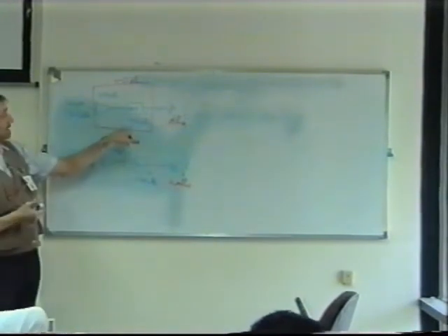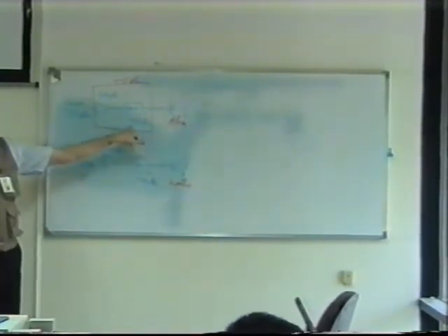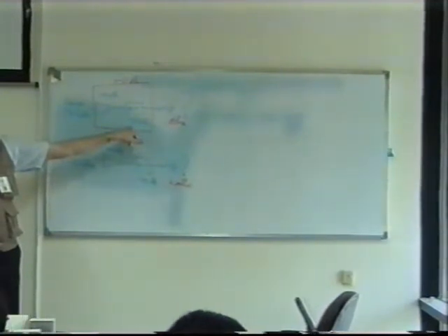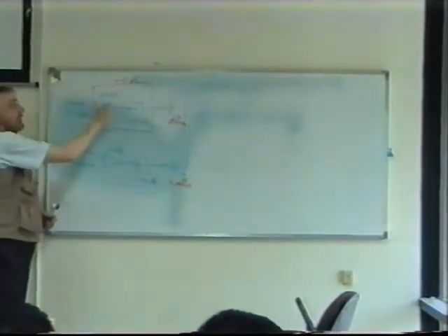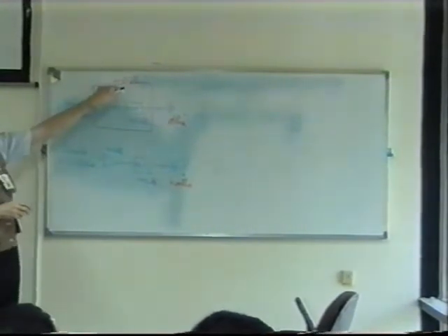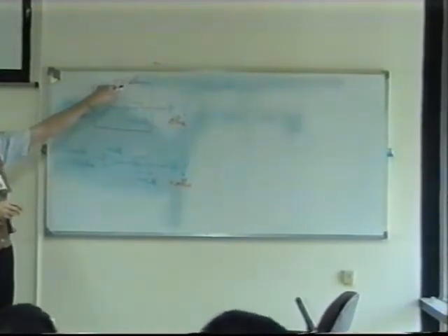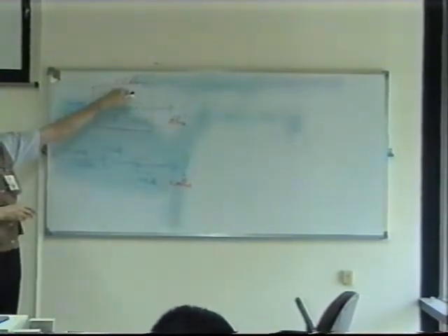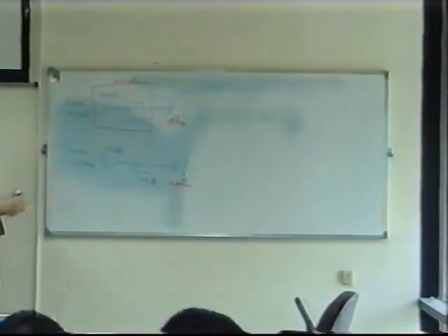And minus 60 dBs is 10 to the minus 6. Now, to get the total, mathematically, you can take the difference in the indices. In other words, 10 to the power 4, or 40 dBs is the gain. 100 minus 60, 40.